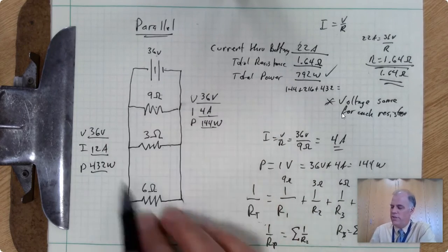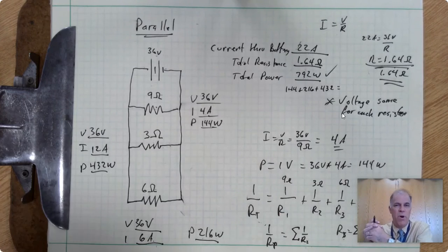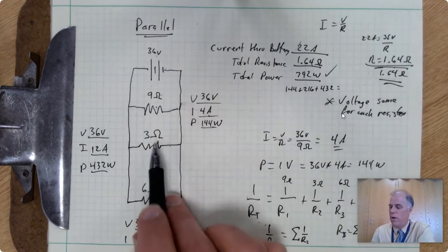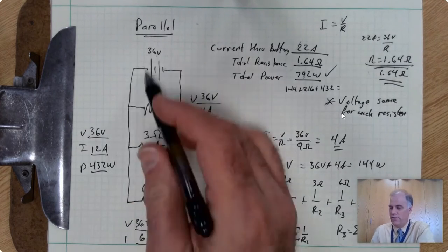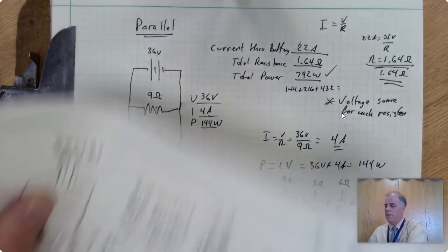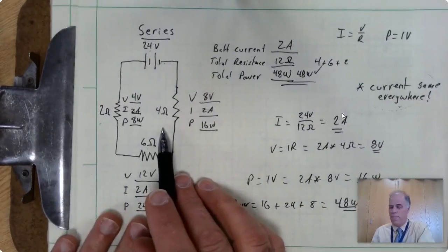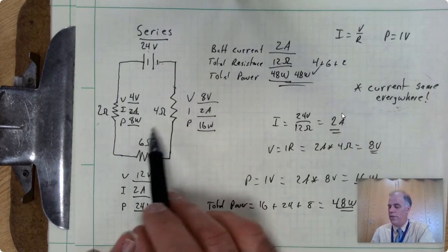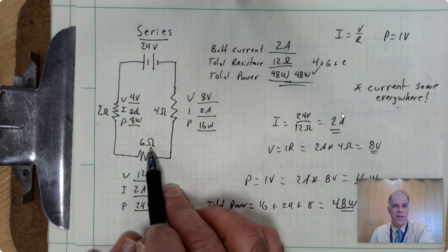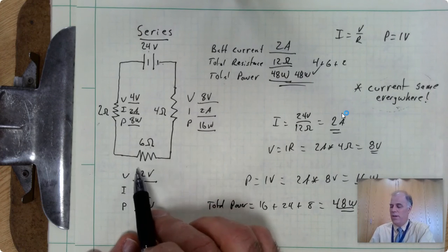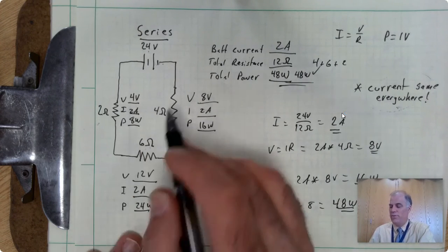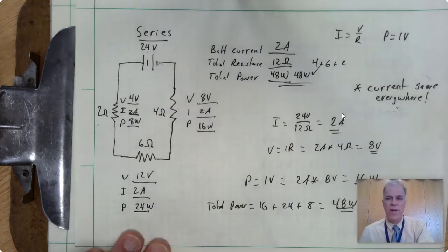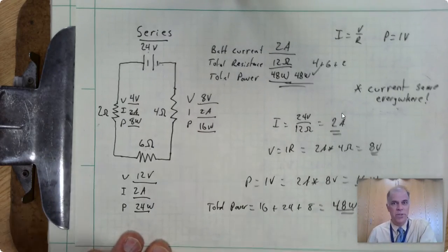So the equivalent resistance, the equivalent of how big or how small the actual pipe is, that total resistance, will be smaller than the smallest resistance in parallel. In contrast, for a series circuit, the total resistance is always going to be larger than the largest resistor in the circuit, because each individual resistor is making it smaller and smaller and smaller, making it harder for the current to get through. So one final check on the reasonableness of the answer that you get.